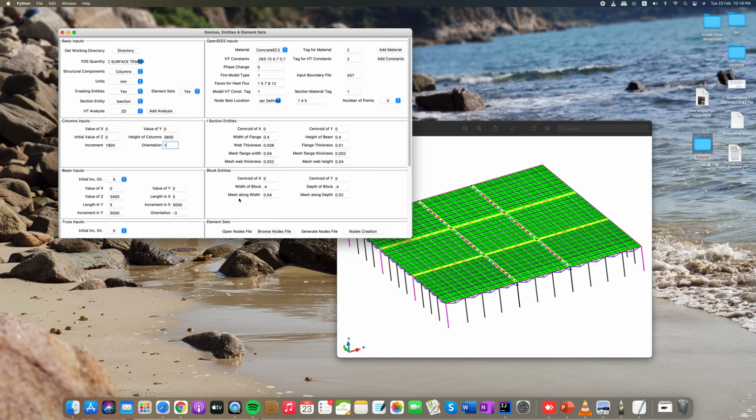If you are choosing the negative direction, meaning below, you have to give -1. Similarly 2 for y, -2 for -y, and 3 for z, -3 for negative z. So this is 1, 2, 3, and -1, -2, -3.